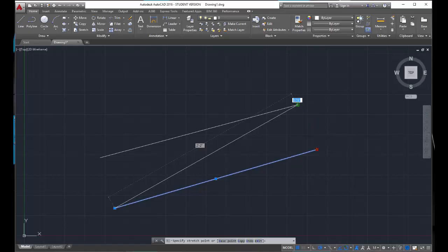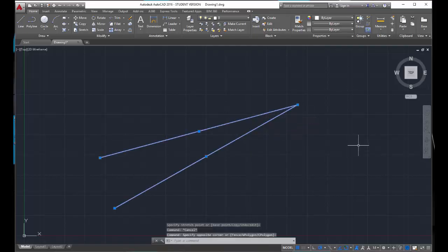So then I click, I hit escape, and you'll see that the two lines have connected together. Pretty simple, right? So anytime that you see a green shape when you're trying to connect your objects together, CAD is basically going to snap it into place wherever it is that you are about to draw at on that point. So let's try this again.